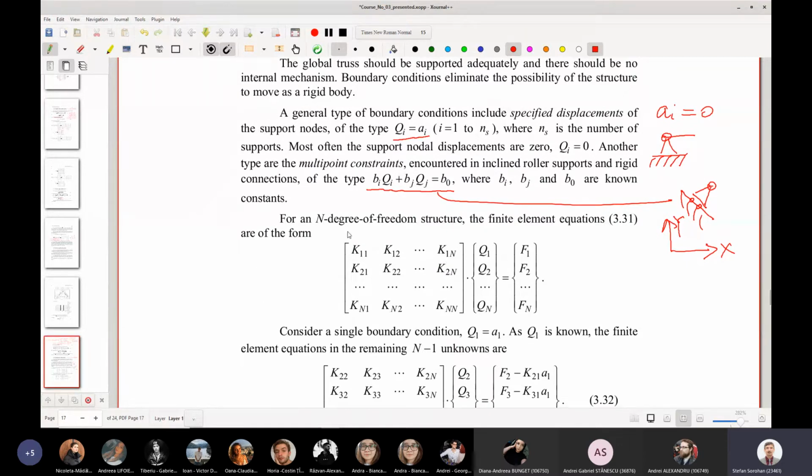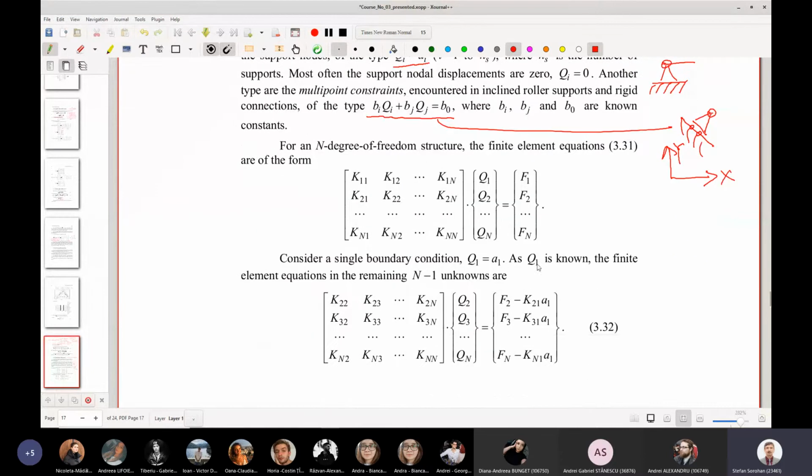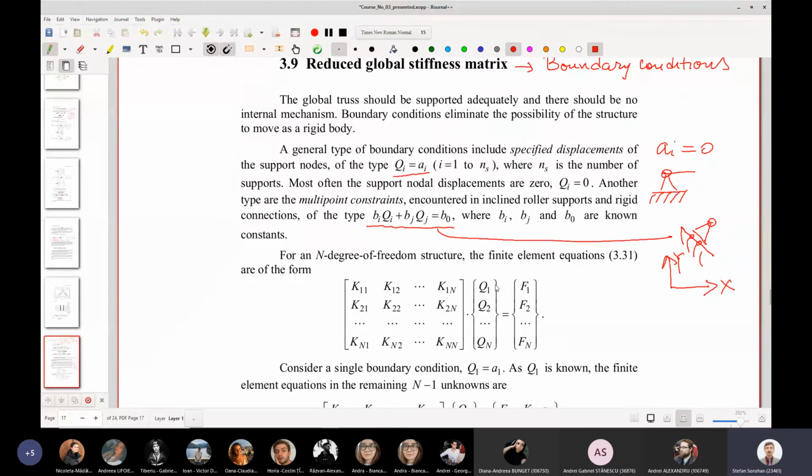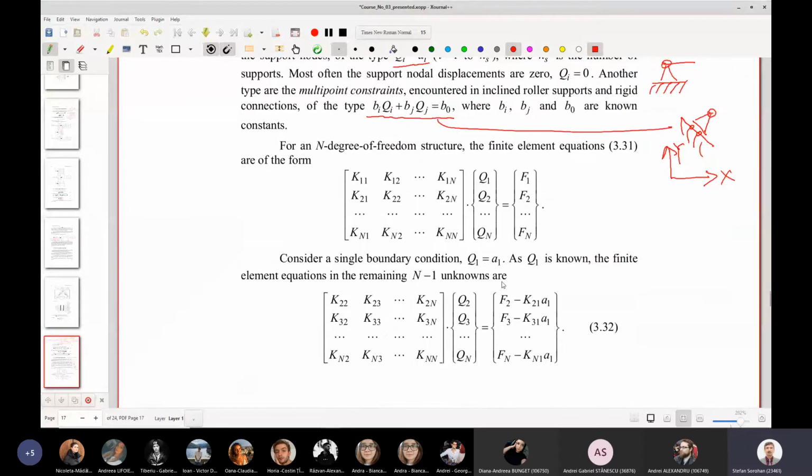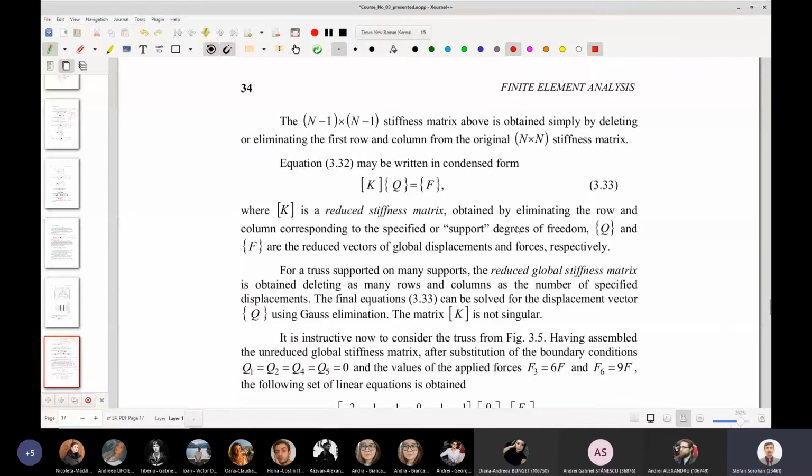And the idea is, okay, if you rewrite the equilibrium, you can take this boundary and you will obtain a new system. This is some mathematics; if you want, I will neglect presenting it in detail. So the main idea is, after imposing the boundary condition, you can obtain a new relationship in which the stiffness matrix is reduced, and that means this K without bar is a reduced stiffness matrix. And this one is no more singular. This is the main idea.